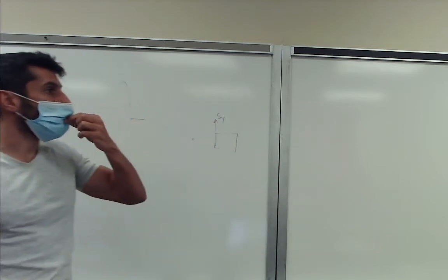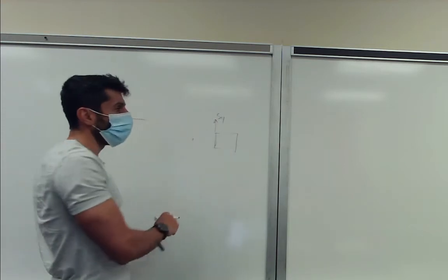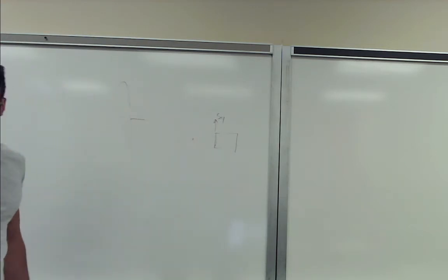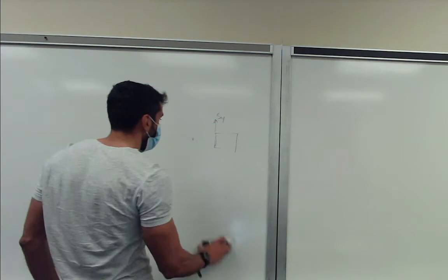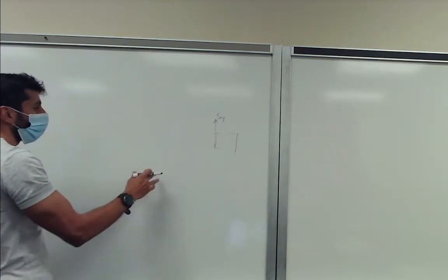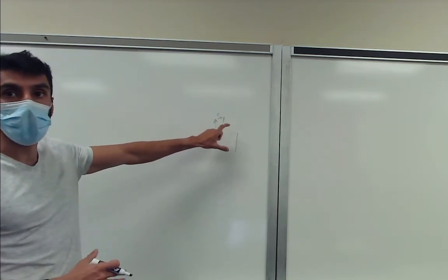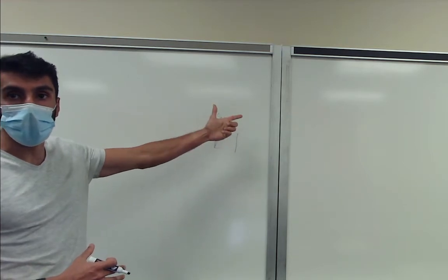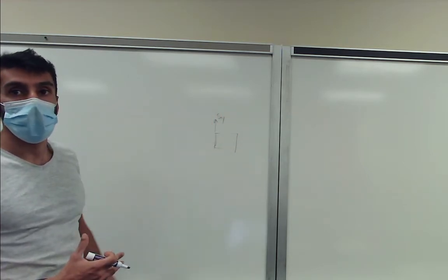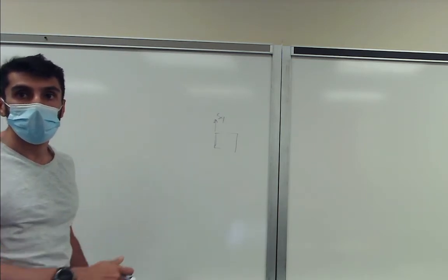But we will assume in most cases, for the shear flows, we really don't care where it lies. We will just do the calculations because the location of the shear center doesn't affect your shear flows, the flow direction or the magnitude. It doesn't affect those. It's just affecting whether the structure bends and twists or just bends.